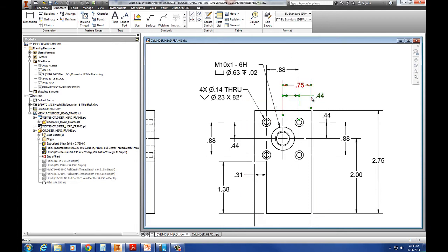Extension lines can cross extension lines. We cannot cross a dimension line. The dimension line surrounds the dimension, if you can remember it that way. That's the ASME standard. So I'm just going to make sure that I've got all these pulled out. I'm sorry to take you guys through this because you may remember this, but better safe than sorry. Alright. Okay, so we have all those located. Here's another one. If they're overlapping, you're going to have two that you're going to have to do this way, unfortunately.